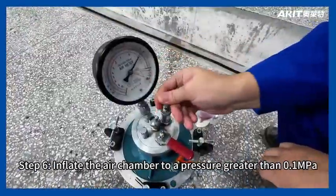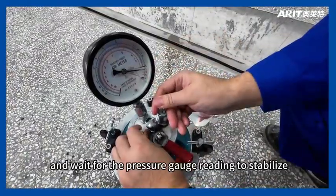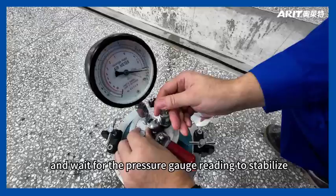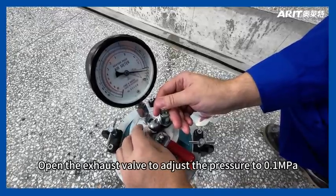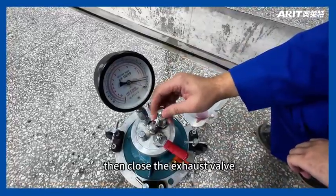Step 6. Inflate the air chamber to a pressure greater than 0.1 megapascal, and wait for the pressure gauge reading to stabilize. Open the exhaust valve to adjust the pressure to 0.1 megapascal, then close the exhaust valve.